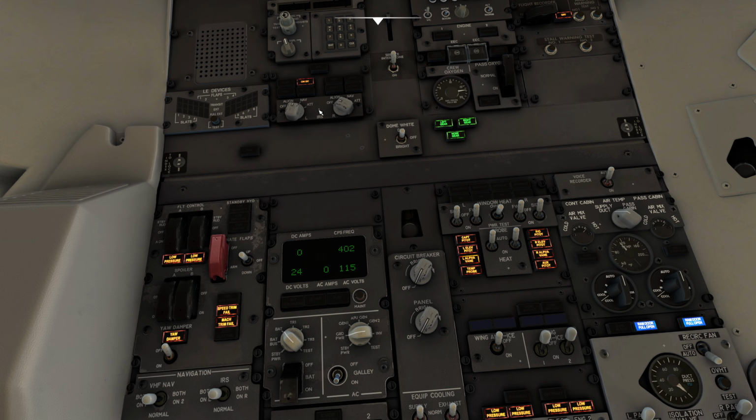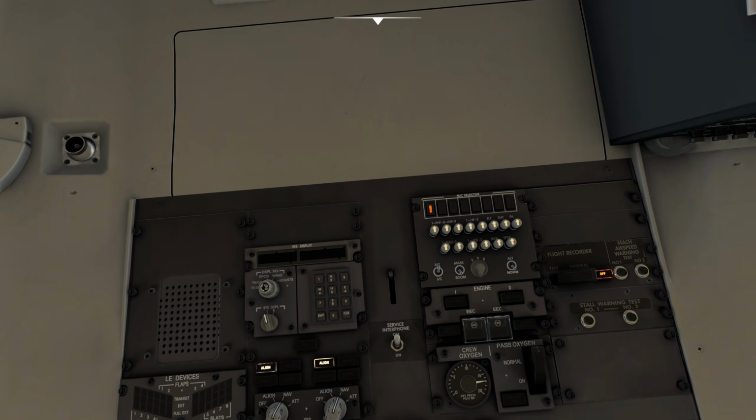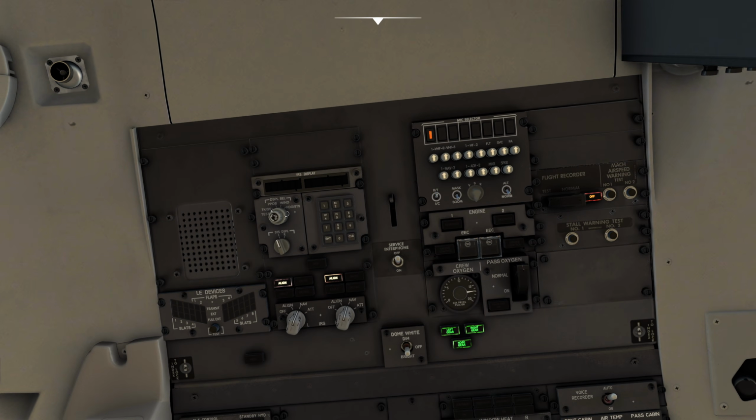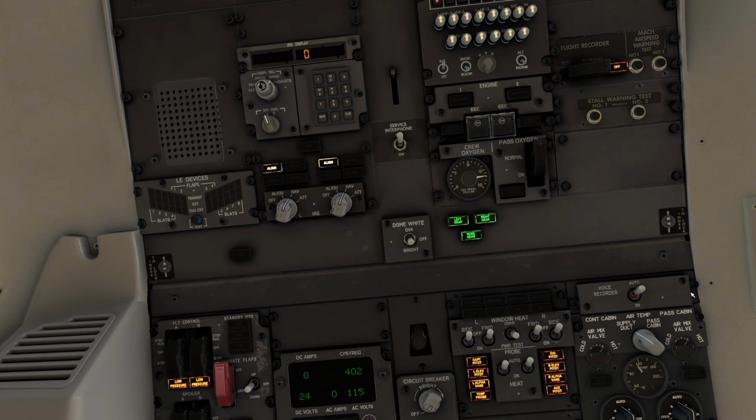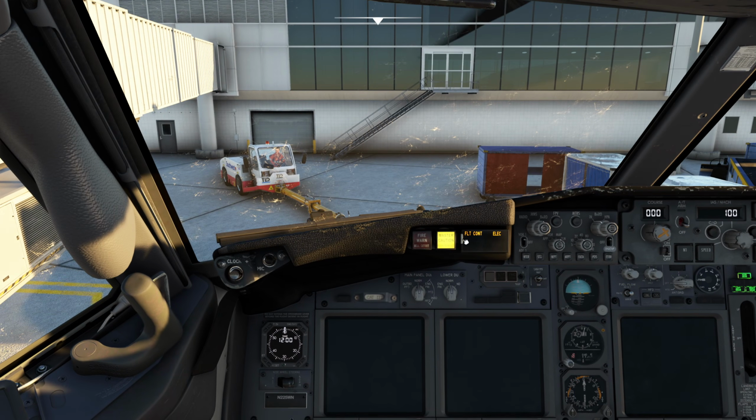That is the IRS that's going to be our navigational system, and we're going to use that to find our way to Dallas. So we'll just switch this over to heading STS. What this is going to do is give us a countdown in minutes until the IRS is aligned. Basically, I have it set up so that it aligns really quickly so we don't have to wait for that. Okay, jumping back down into the cockpit, we can disable the master caution.